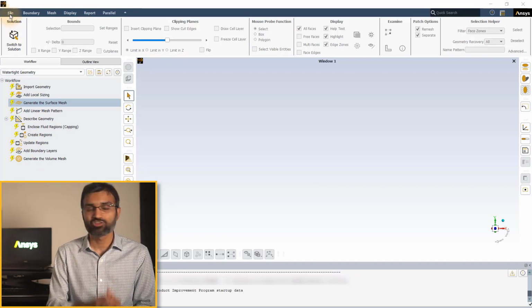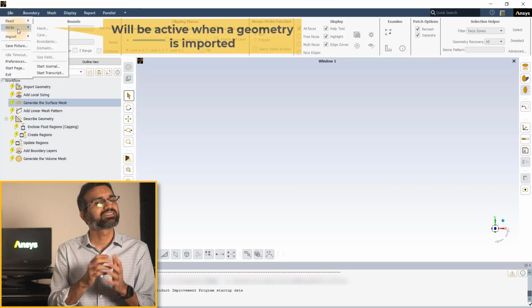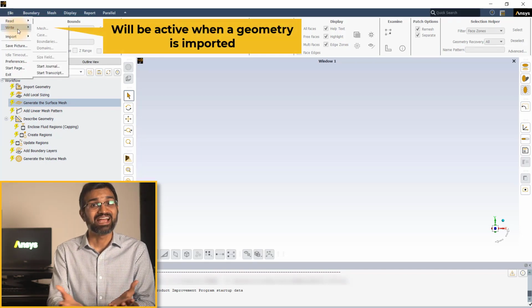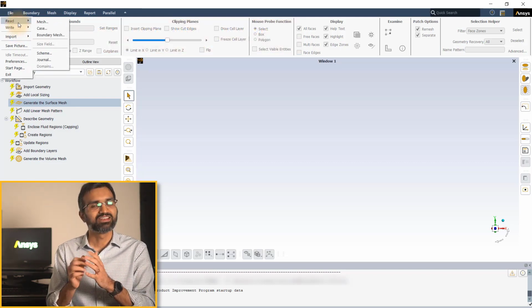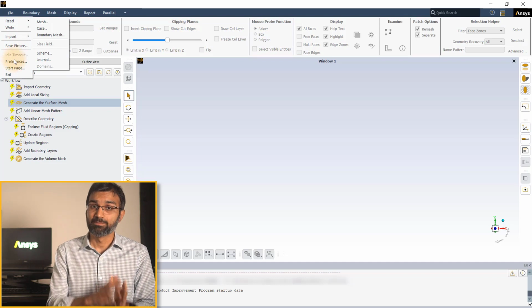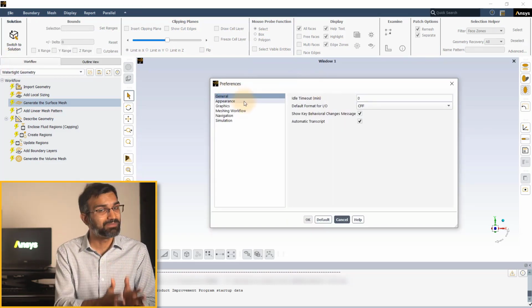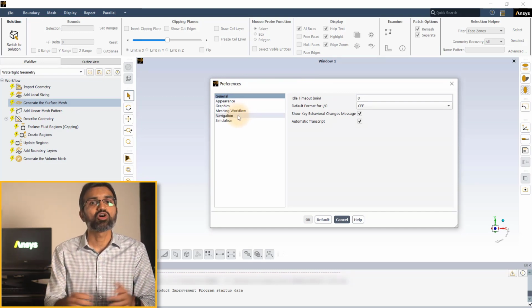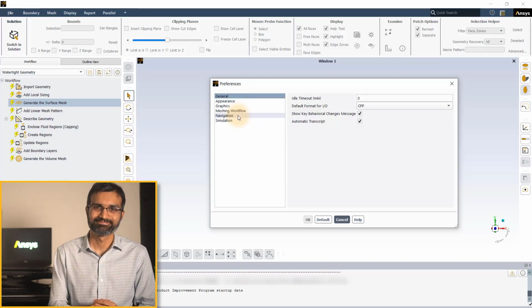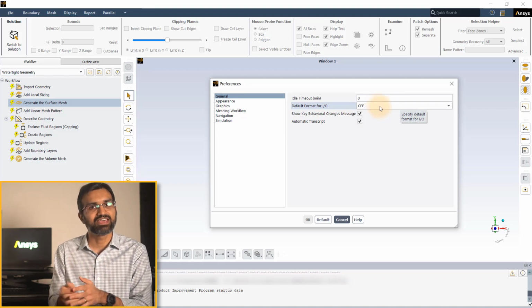You can also save your mesh at any point by going to the File menu and choosing to write the mesh. Also, an existing mesh could be read into the Fluent Meshing session using the Read option. With the Preferences dialog box, you can specify the global settings related to appearance, graphics, and navigation that are applied whenever you launch a Fluent Meshing session. To read or write mesh files, Fluent uses the Common Fluids format, CFF, by default.